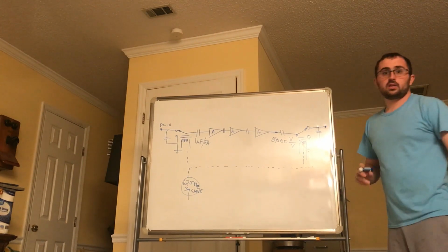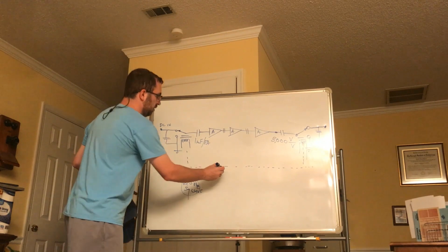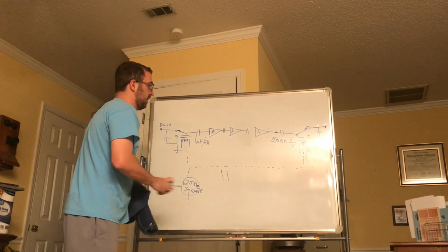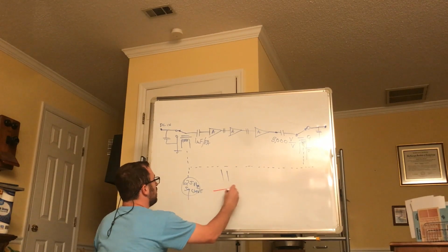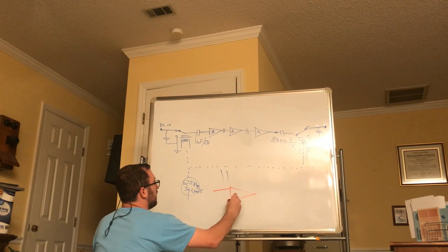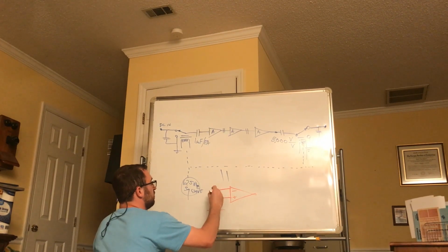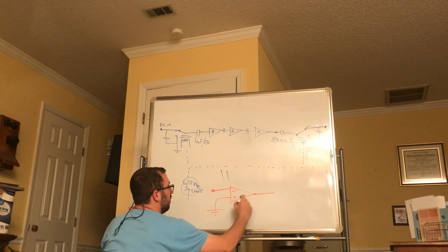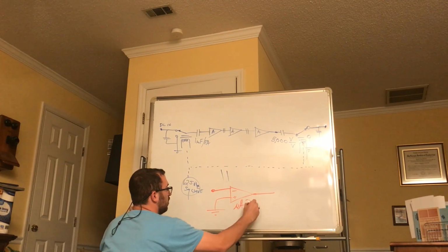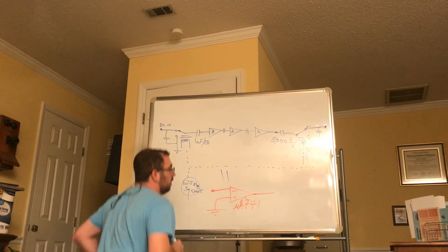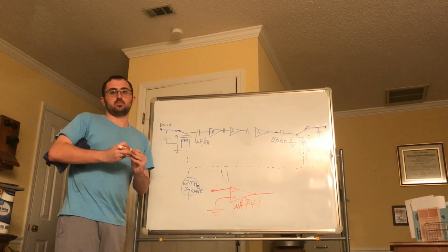So one way to amplify DC is as an op amp would do, and this entire circuit actually behaves like an op amp, where you have the positive lead at ground and your negative is your input. And this would probably behave something like a UA 741. Okay, so now you might wonder, well, it has a gain of 8,000 volts per volt.